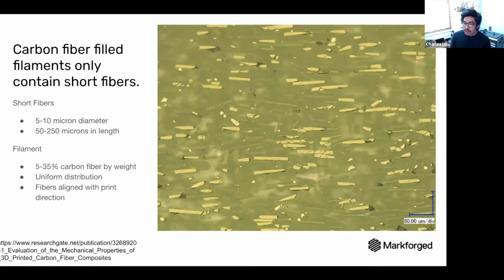And you're going to see them vary anywhere from 50 to 250 microns in length. Now, you might see some companies make a specialty one that says, oh, we use very fine powdered carbon. Powdered carbon gives you some different characteristics. And then some might try to go even longer than 250. But from what I've seen in the market, 50 to 250 micron length is about right. If you go any longer, it gets harder to print. If you go any shorter, then you're just adding maybe a more conductive filler, not necessarily adding much to strength, maybe some bulk stiffness.